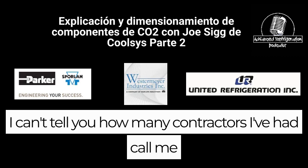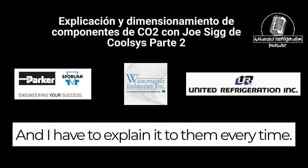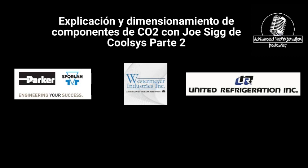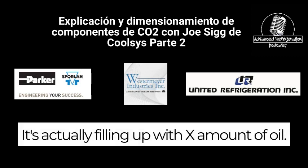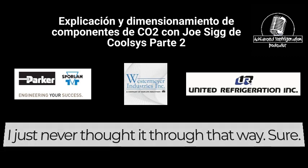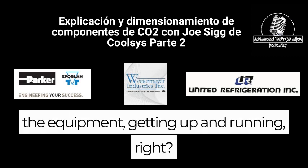Okay. And I can't tell you how many contractors have called me and asked, why are you specing double risers? I don't get it. And I have to explain it to them every time why we put them in and how they work. I got why they worked, because you're wanting that, but I just didn't think, okay, it's actually filling up with X amount of oil. Once it fills up with oil, then it blocks it, causes the restriction, which would cause the refrigerant to go up. I just never thought it through that way. Sure. And most contractors won't. No fault to you guys because you're in there to install the equipment, get it up and running, right?